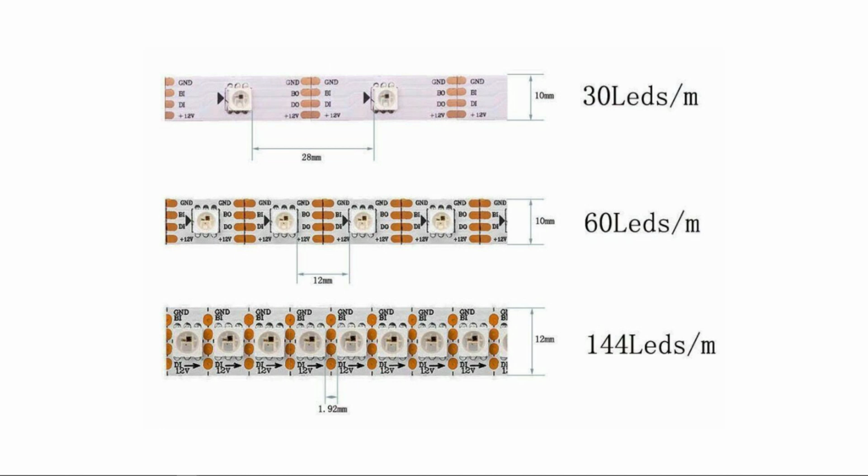So you look right above it, 60 LEDs, that's a much better distribution, and that gives you some space to actually put them into connectors. And then of course the 30 LEDs, that's spread out. So it's up to you to determine what kind of density you need. And if you have too much density, then you just spent more money on it than you had to, and you're going to have to use a larger power supply.